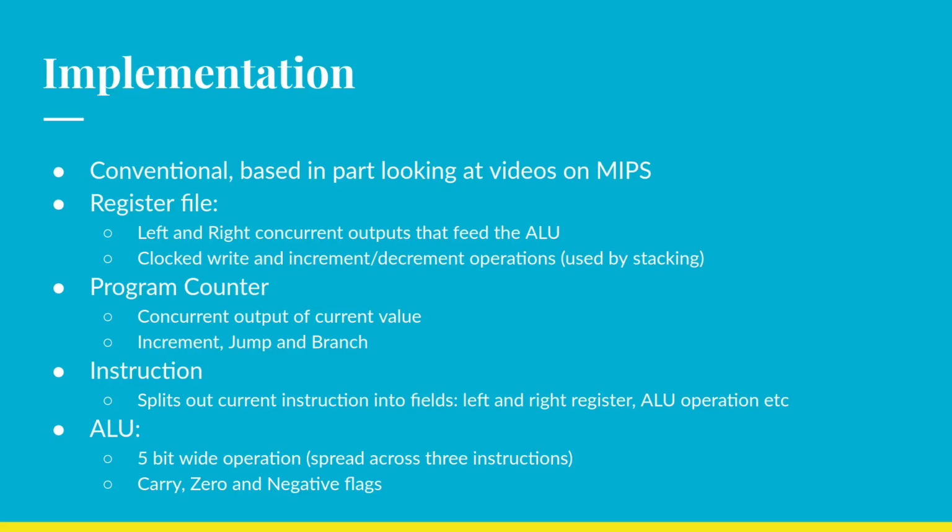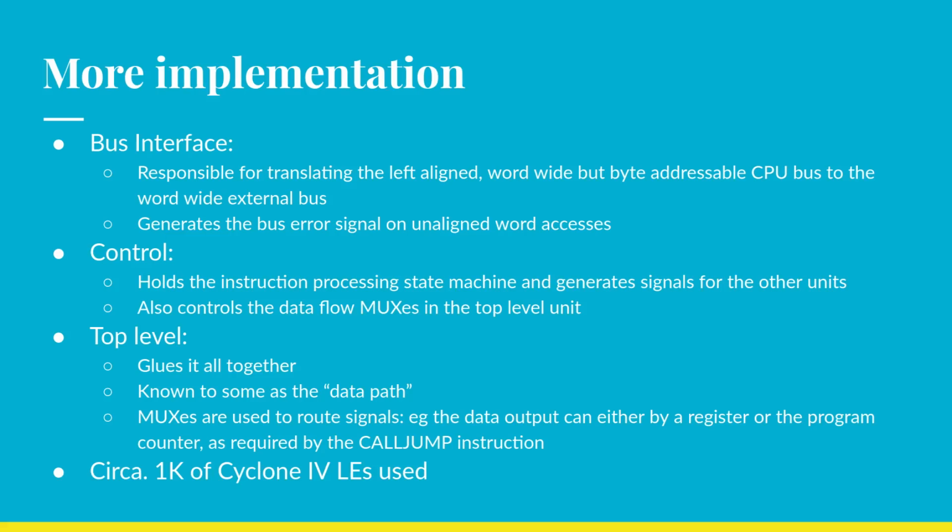The other one is for when the operand comes from a register, and the third variant is when you don't have an operand, so things like bitwise not, increment, and so on. They use a separate set of 16 ALU operations essentially, and that outputs the three different flags. Seem to be 4 flags, hopefully, when I implement overflow.